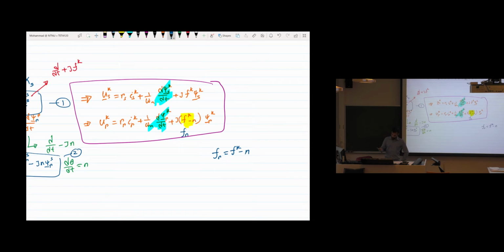Later we will see that if this fr is 0, then there is no torque. So in order to produce torque in this machine, squirrel cage or the induction machine, there must be some speed difference between the stator voltage frequency and the rotor speed frequency. If there is a difference, then you will get torque. That's one important thing to remember for now.